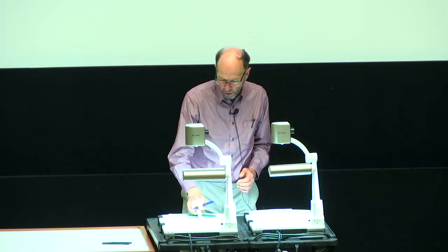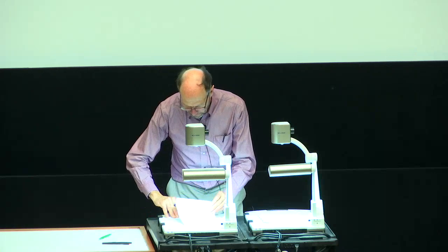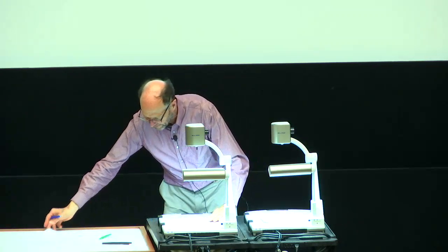You might even have another resistor here that goes to ground or so. If you would buy a bad op-amp, then there might be current flowing. I don't know whether this is helpful. I mean, all I want to say is that we could certainly have also some kind of a contraption where this current wouldn't be 0. But in EECS 16A, the operational amplifiers are all ideal, so these currents are 0. Okay? So on the final, or whatever, on the exam, please do not get confused. The current's going to be 0.